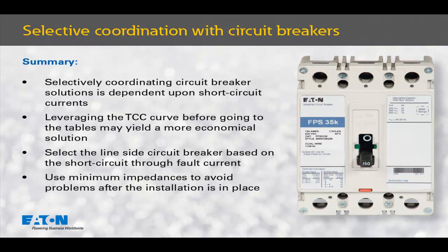And remember, use minimum impedances and short conductor lengths to avoid problems after the installation is in place. Fixing selective coordination issues after the design is done and installed can get expensive quick.